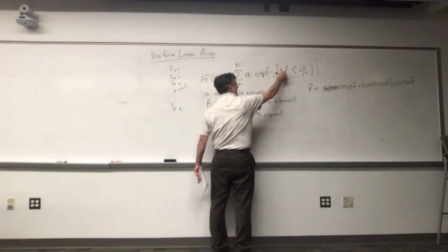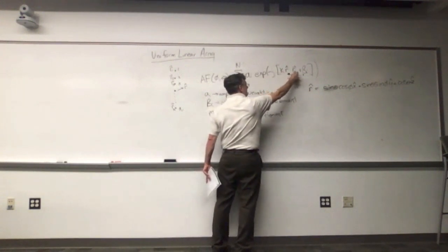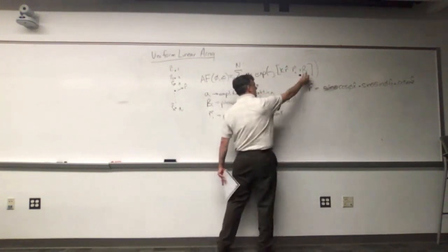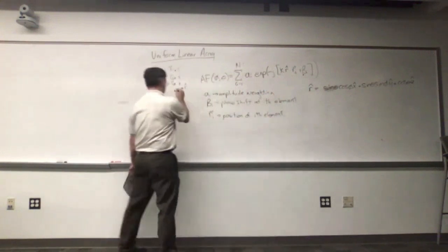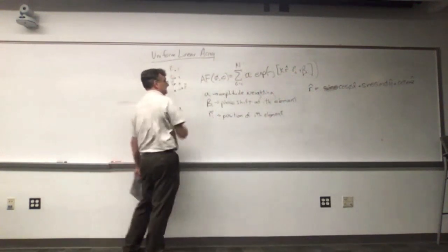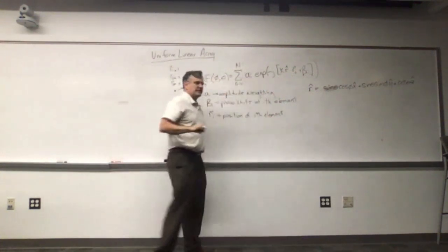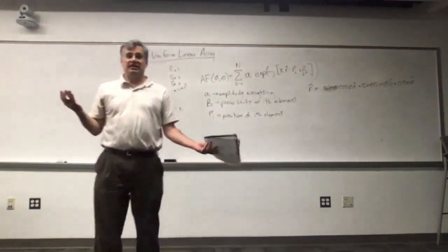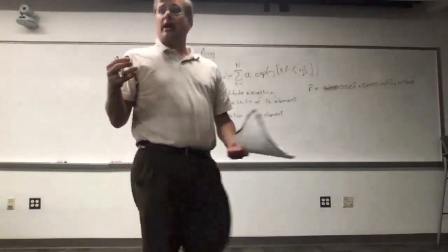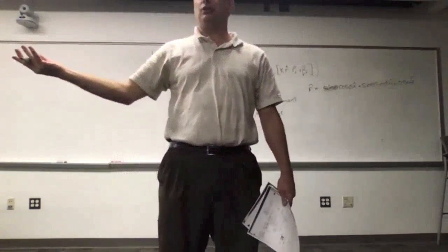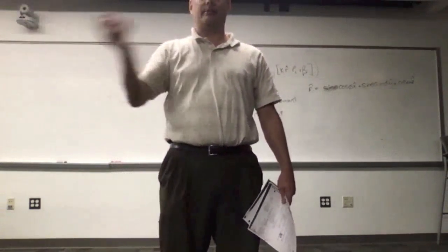So we say all of our orientation dependencies are actually wrapped up in here. We put in the wavelength, 2 pi over lambda, the positions of all of our array elements, the phase shifts that we want to introduce to all these different elements. And then the weighting, we haven't talked about a weighting yet, but there's nothing that says I can't build an array where I only put half the amplitude in one element that I put in the other.